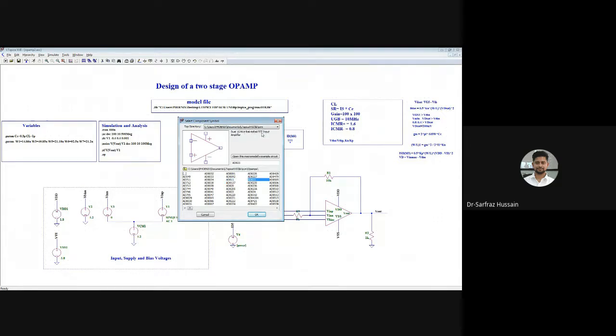So here you can see rail-to-rail FET input amplifiers are there. So a lot of design circuits are there. ADCs also, there are a lot of ADCs. These are all Analog Devices ADCs, and you can just make use of that. You can even try to find out the parameters of an ADC also. If you want to calculate the effective number of bits, find out the errors, calculate the bit error rate, or the signal-to-noise ratio, all these things you can calculate.